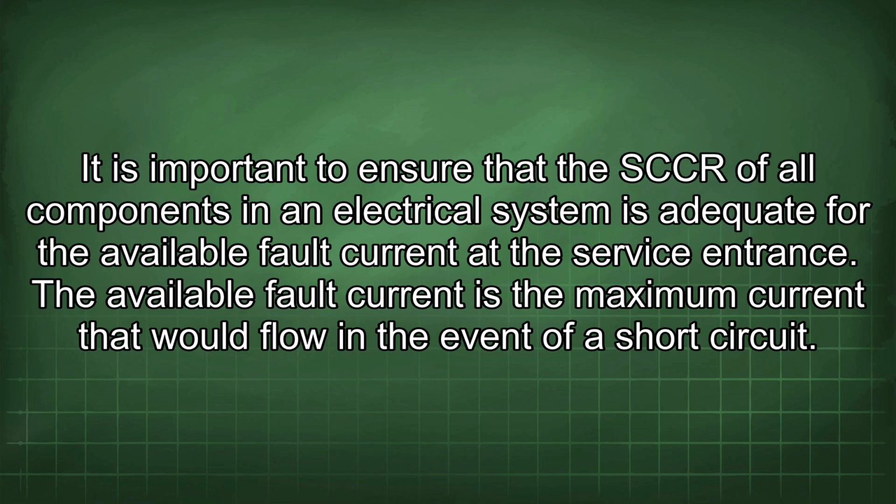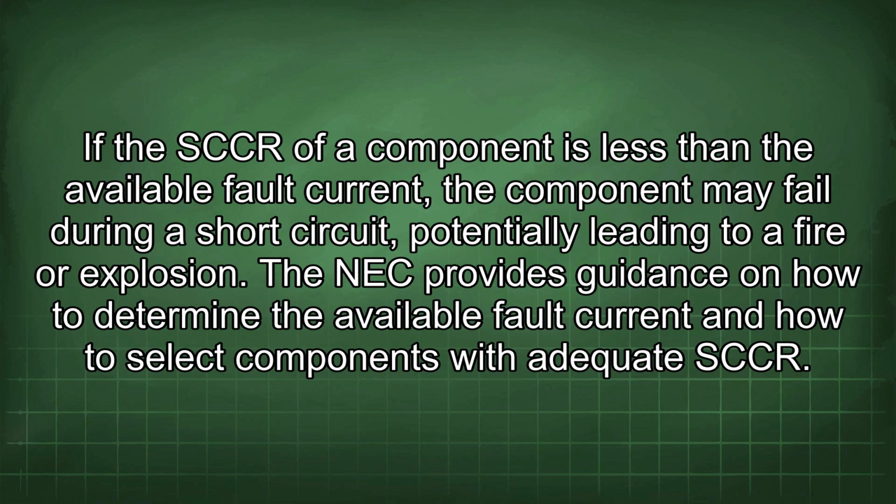The available fault current is the maximum current that would flow in the event of a short circuit. If the SCCR of a component is less than the available fault current, the component may fail during a short circuit, potentially leading to fire or explosion. The NEC provides guidance on how to determine the available fault current and how to select components with adequate SCCR.